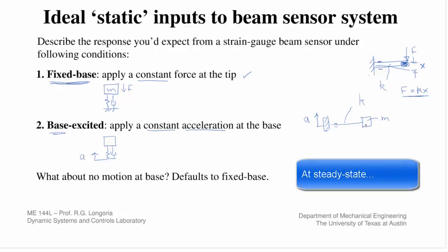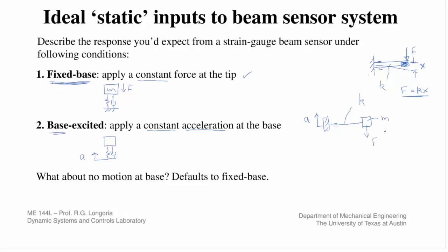So you're going to feel a downward force here. It's going to look a lot like this system. So it's going to deflect, and the output's going to be a constant voltage. That deflection induces the strain, which causes a voltage output from the strain gauge instrumentation. So this force here is an inertial force. That's the mass times the same acceleration that you're trying to measure here. Okay.